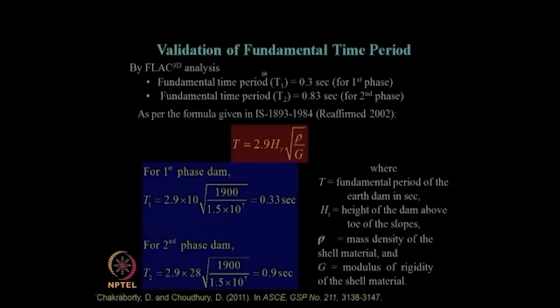Also, we need to calculate the fundamental time period of the entire system, or the entire tailing dam. To calculate that, FLAC 3D analysis directly gives us the results of the fundamental time period. This is for the first phase of the dam, this is for the second phase when it is 28 meter height. What are the fundamental time periods?